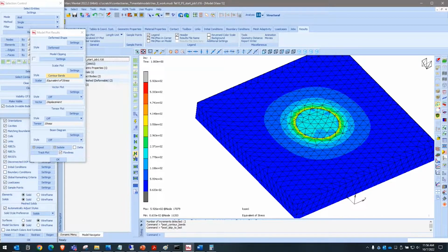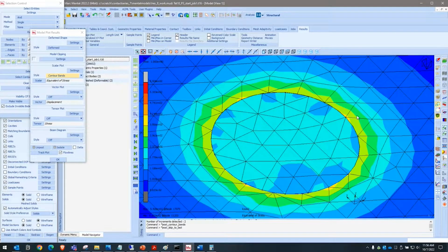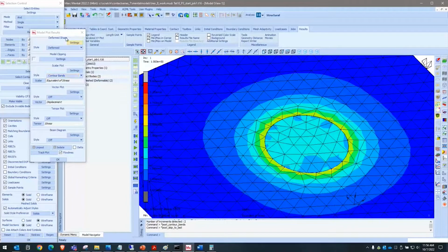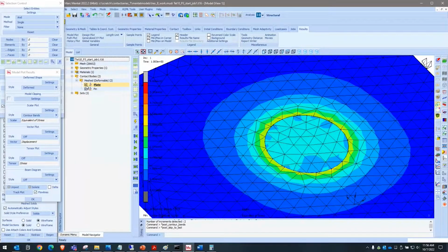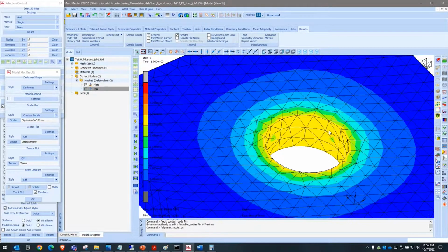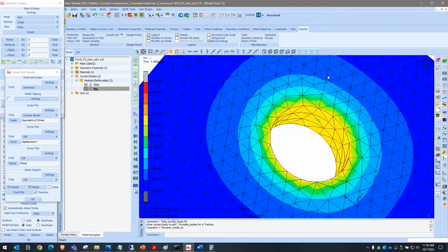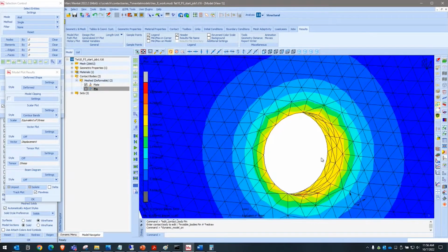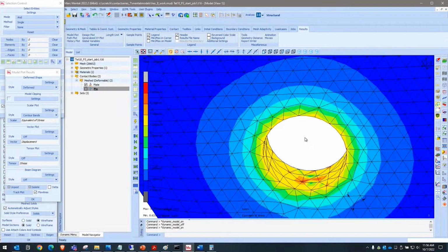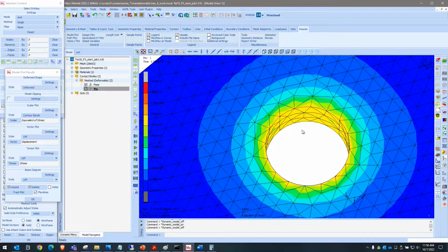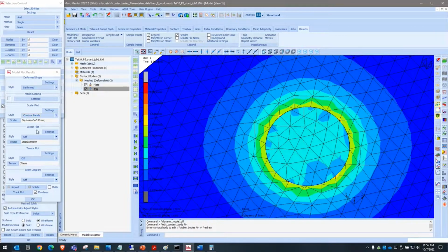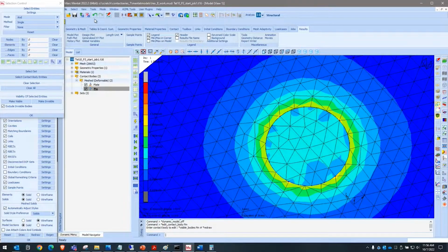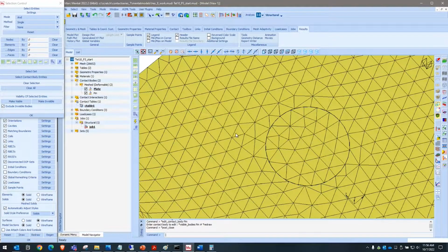Yeah, and we get this kind of garbage. So we're back to about 600 MPa, which is ridiculous, but from the pattern, it's pretty clear that something is severely wrong. And if we switch off the pin, I expect to see some weird stresses inside over there. Okay, so all of this is due to slight overlaps in some regions and some slight gaps initially due to that slightly bad mesh.